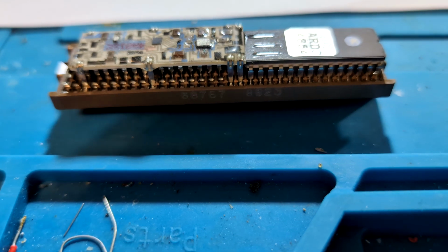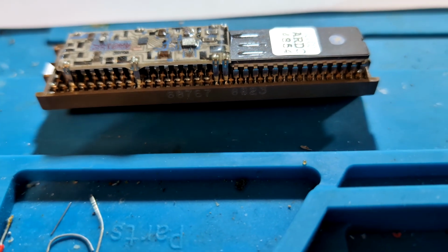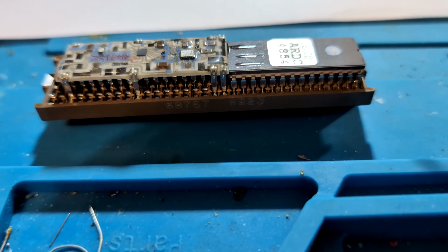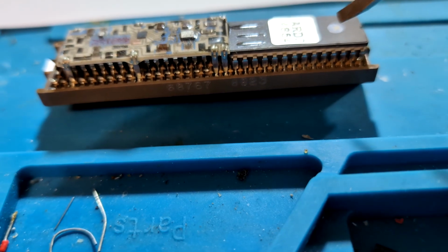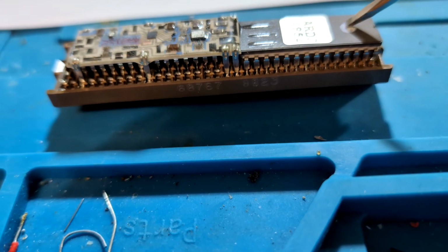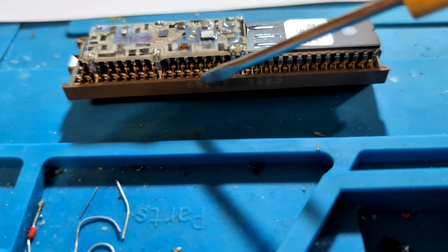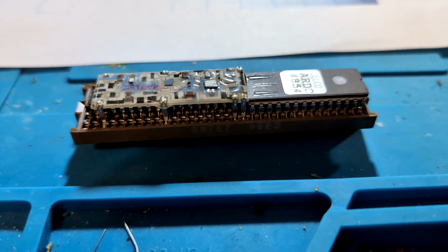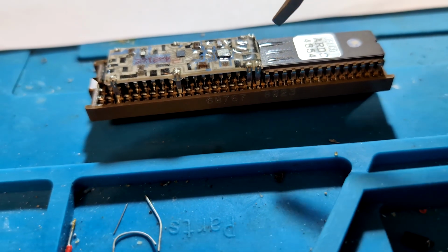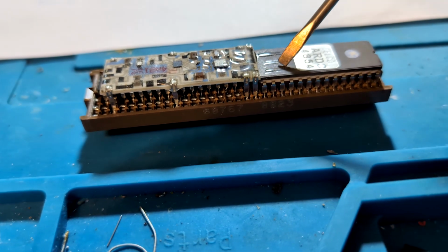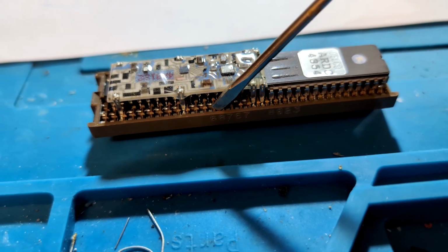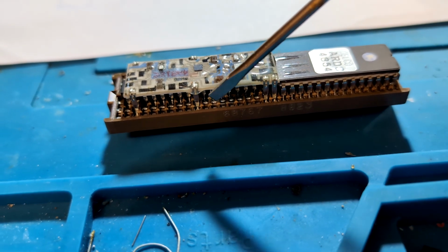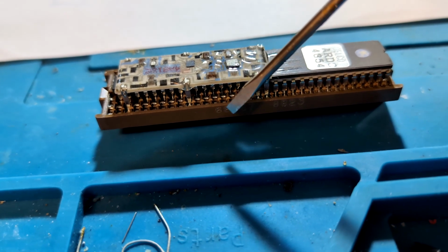What you can do in that case is pretty simple. You can jumper a couple of pins, and that, well, it won't fake it out, but it will set this Memcal up to fire as a V8 Memcal would.